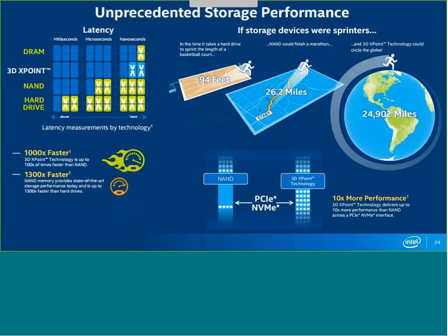And last but not least, if you're looking at the left, and this is primarily the most important part, DRAM talks about latencies in nanoseconds. We're looking at NAND, it's in microseconds, and then hard drives, spinning disks, are milliseconds. So looking at 3D XPoint, you're in the speed of nanoseconds with the lower cost of NAND today and so on. The performance charts, everybody's claiming are off the chart, and just keep your eyes open for this.